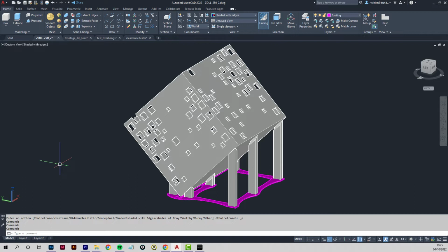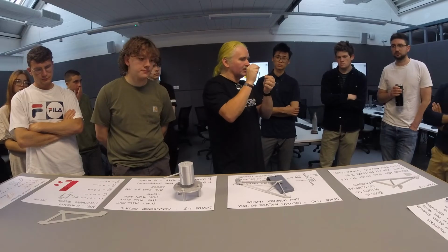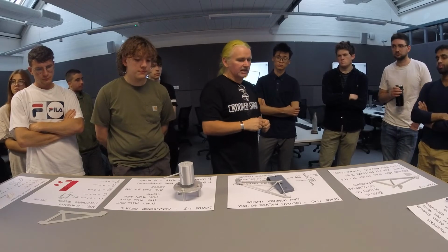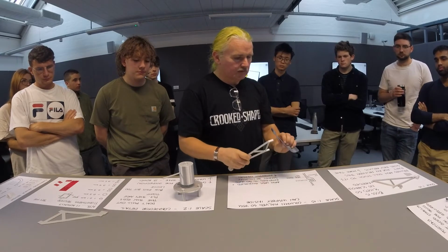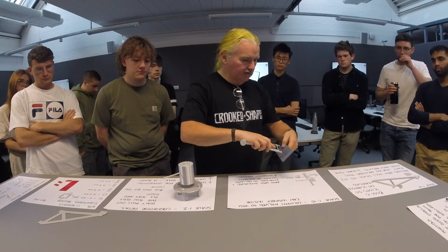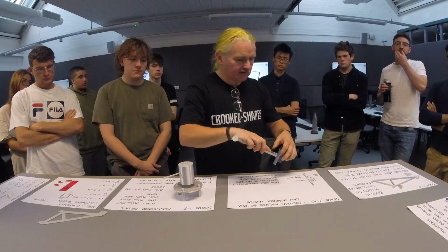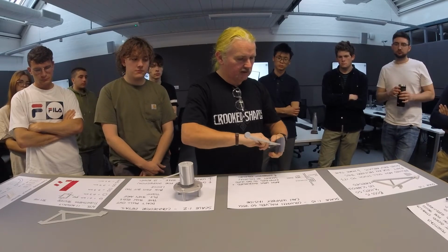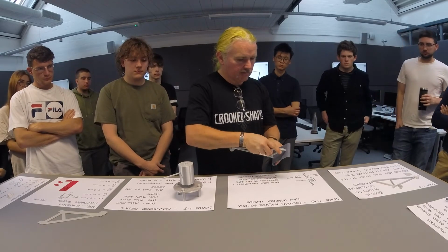It was beyond what the software could recognise as unstable. It was completely unstable. And so I just modelled some little legs that you can snap off, and a little bit of sanding and clean it up. But it's a really great way of making models, but there are a few things to bear in mind.